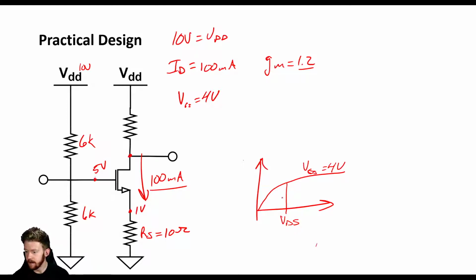If our VDS gets below about 2 volts, whenever we increase our VGS, we're going to be decreasing our VDS, and that's actually going to cause second order effects to happen. So our VDS and our VGS are both going to be impacting our output, which is not good. So that's going to cause a lot of wonky things to happen.